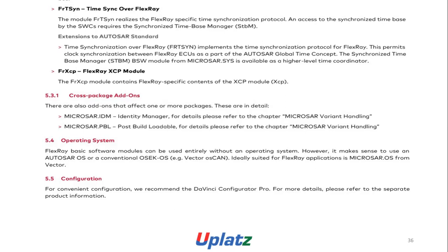In cross-package add-ons, there are also add-ons that affect one or more packages. These are in detail: MICROSAR IDM, Identity Manager. For details, please refer to the chapter MICROSAR Variant Handling. MICROSAR PBL, Post-Build Loadable. For details, refer to MICROSAR Variant Handling. Operating system: FlexRay basic software modules can be used entirely without an operating system.